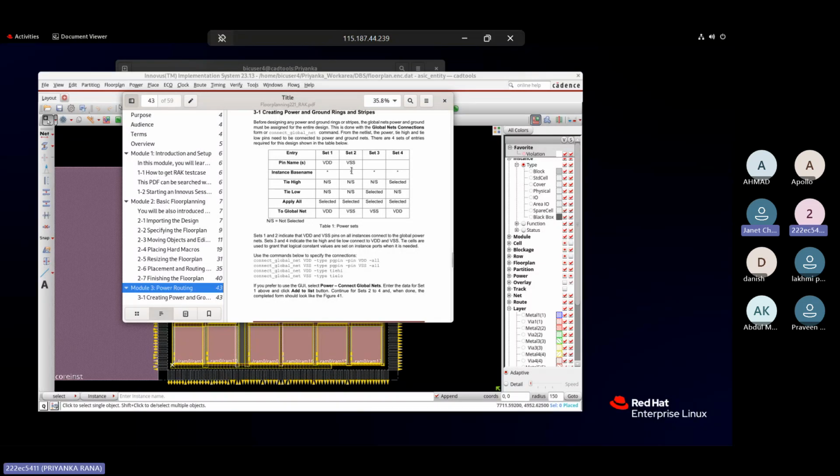And we are going to add one type of physical cell called tie low and tie high cells. Now this is one important physical cell. What do tie low and tie high cells mean? These are basically stabilizers that we use. These tie low and tie high cells will save our transistors if there is any voltage spike in the power connection. So any power or ground connection going to the transistors will go through these tie high or tie low cells.